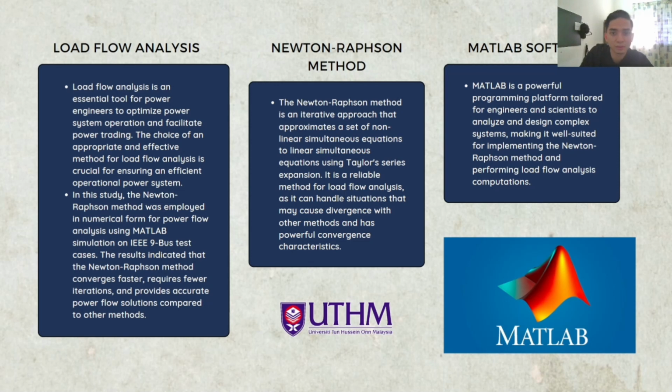Okay, the Newton-Raphson method is an iterative approach that approximates a set of non-linear simultaneous equations to linear simultaneous equations using Taylor's series expansions. It is a reliable method for load flow analysis as it can handle situations that may cause divergence with other methods and has powerful convergence characteristics.